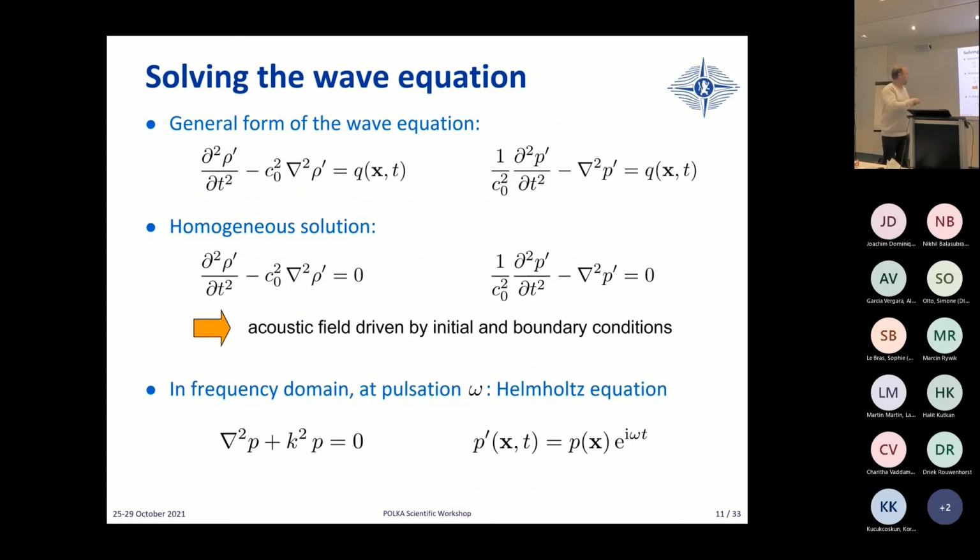Just a quick word on what we are going to do for the duct acoustics part. In particular, we are going to look at the problem in the frequency domain, because it's more convenient to work in the Fourier domain. We will see that it gives you immediately an interpretation of the results in terms of propagating waves and evanescent waves, that is more practically usable.